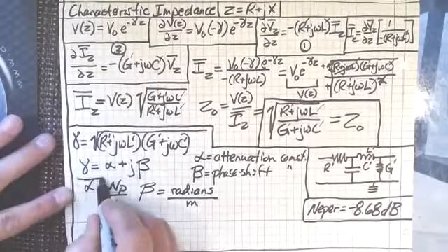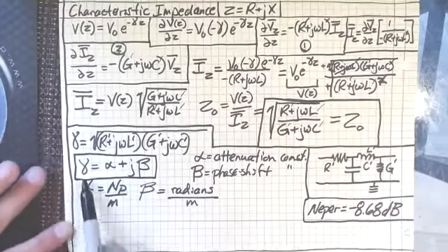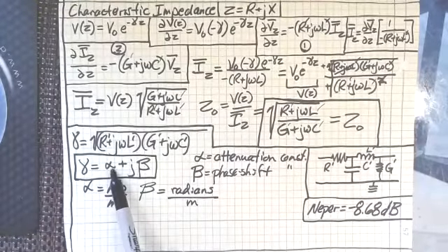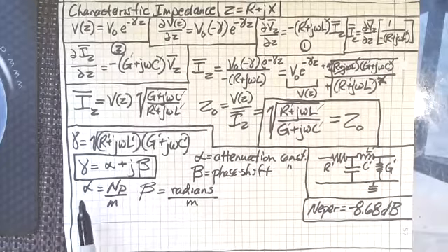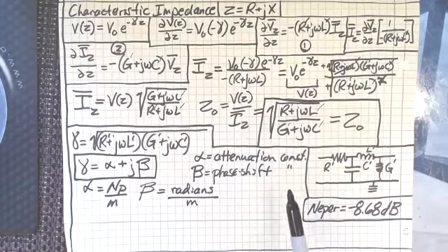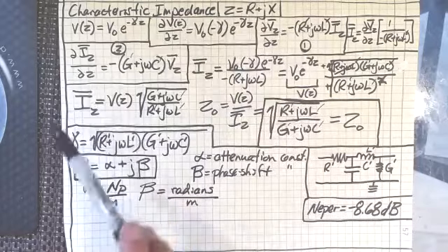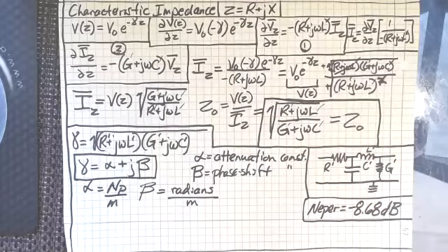And anyway, we'll get into that a lot more because let's face it, this right here is a complex number, so we're working with complex numbers now as to what the propagation constant is. And by finding the attenuation constant, we can tell what the decibel fall off is for any metallic conductor transmission line, whether it's transmitting power or whether it's transmitting signal. You know, if it's a Cat5, if it's a coax, if it's a microwave horn, whatever it is, we can figure it out now because we're going to find out the propagation constants here.